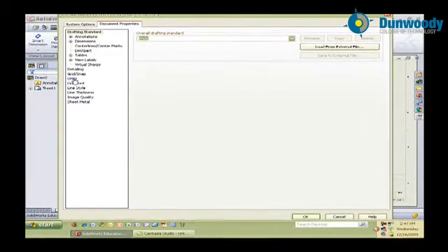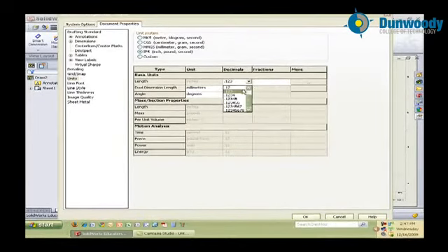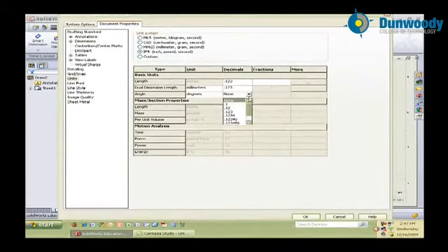And then I'm going to go down and select the units bookmark. And I want to make sure that I have inch, pounds, seconds selected. So make sure that radio button is selected. The length units I want to be 3 place. If they're not 3 place, again, I can just click on the drop down, select the 3 place units, and that'll come up. The angular dimensions I want to be full degrees, so I'm going to select none.